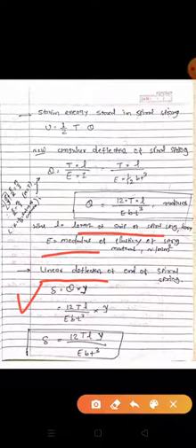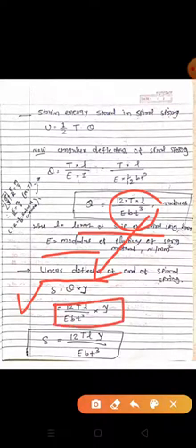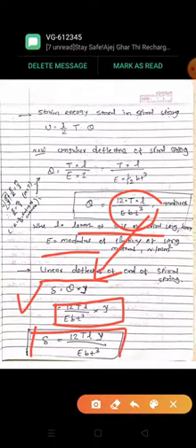We have the value of theta equal to 12 T L upon E b t cube. Putting this value in the equation, delta is equal to 12 T L into y upon E b t cube.